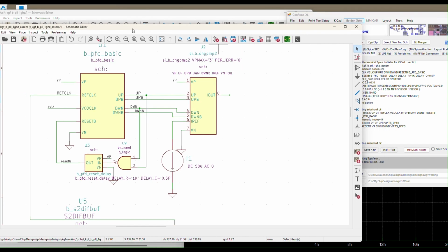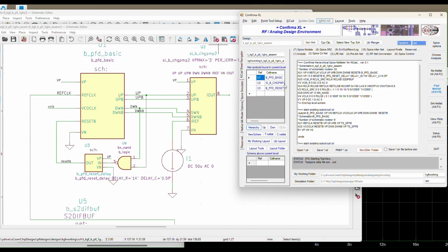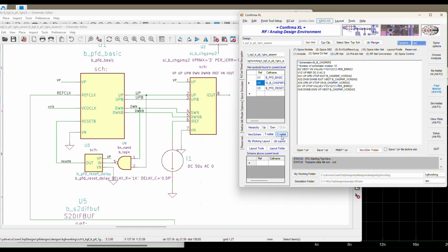I won't focus on that too much. But it's nice to check once in a while, as you're putting down new blocks, and make sure that the blocks you're dropping down are okay. So there's this feature. We have this cell, I clicked on this cell, U2, and I want to see what that cell netlist looks like. So I'll do C netlist.